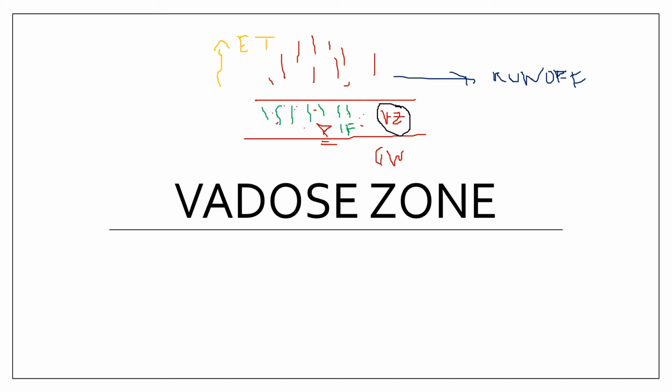because in the vadose zone you have a lot of factors that slow down your movement of water. Okay, so it's a very slow process, which we will be discussing later. Right, so there's a lot of stuff that slows down the movement of water in your vadose zone. But once it reaches your groundwater, you more or less have a fast transmission of water here.